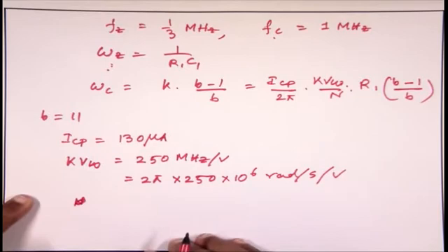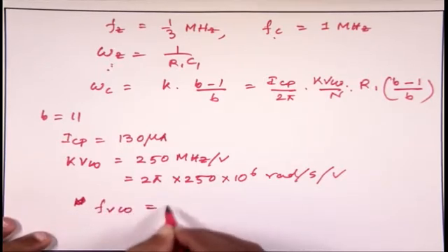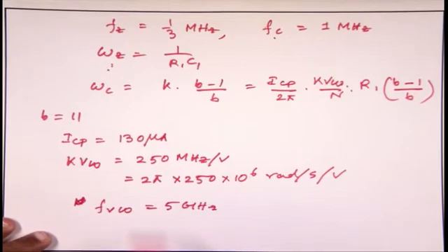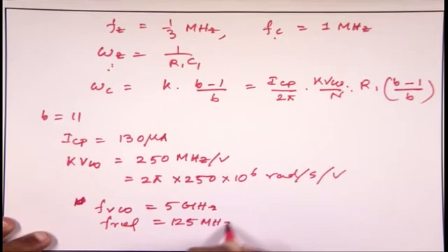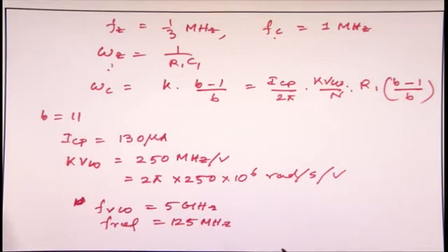So, there is another specification, of course, that is required for the PLL. The first specification: what is your reference frequency, what is the VCO frequency. We have used the FVCO as 5 gigahertz, and we have used the FREF around 125 megahertz. You might ask, why so high? Because this 125 megahertz is generated from another PLL, called a jitter cleaner. I assume that 125 megahertz is readily available. For us, it could be 10 megahertz, 1 megahertz also, whatever.